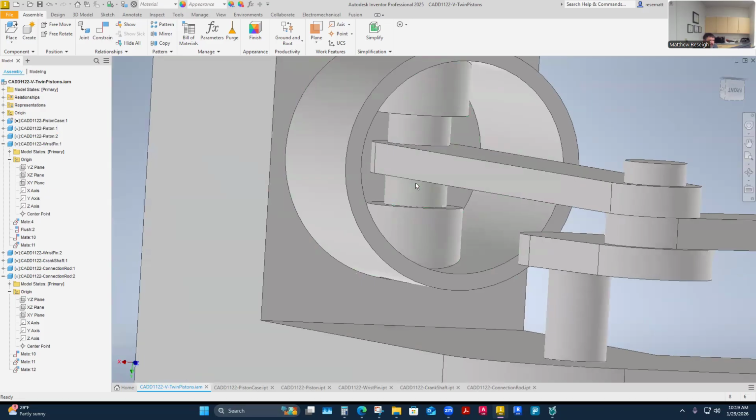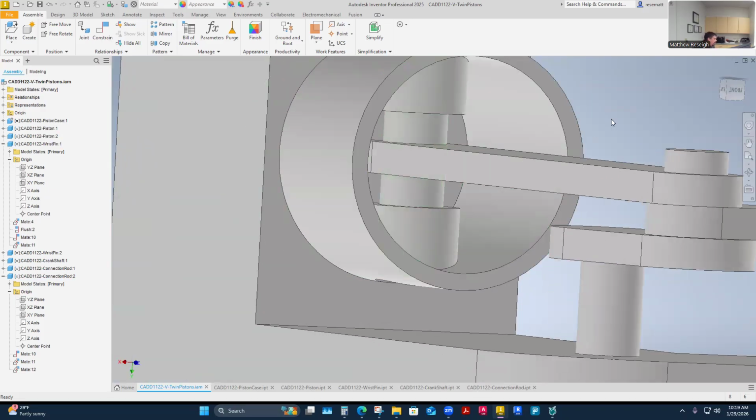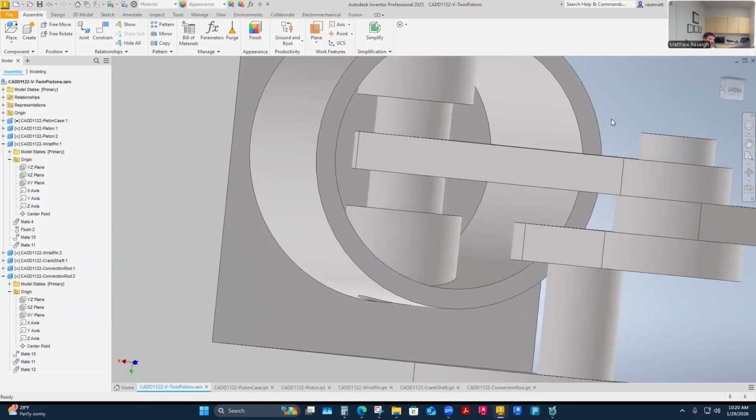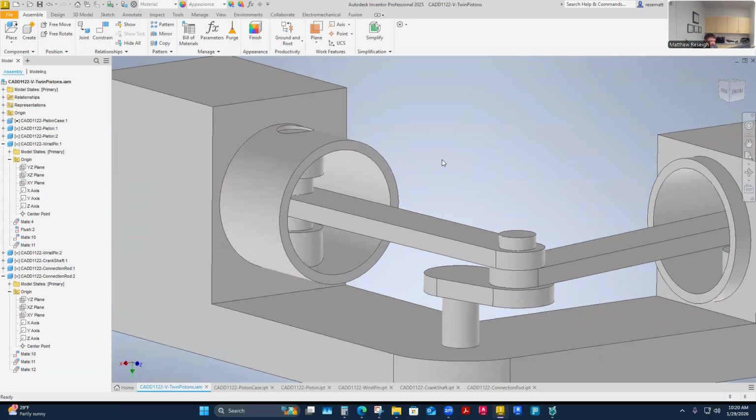And that'll be great. The other thing they make for external snap rings is one that just snaps over the shaft. You don't have to have a special tool or needle nose pliers, but it's open on one side. It just clicks over a shaft. After putting one together, I'd rather have an external snap ring like that, the one where I don't need a special plier. I just need to be able to insert it from this end of the piston and snap them in. So having built a prototype and tried to assemble one, I realized it doesn't work well, and I think I'm going to use a different piece of hardware there.